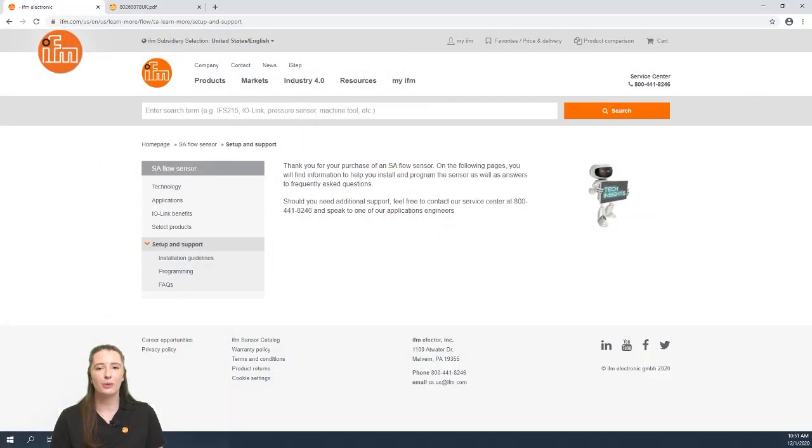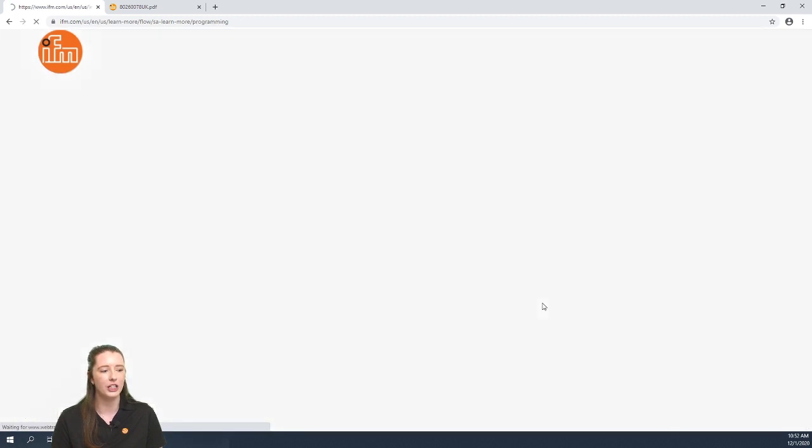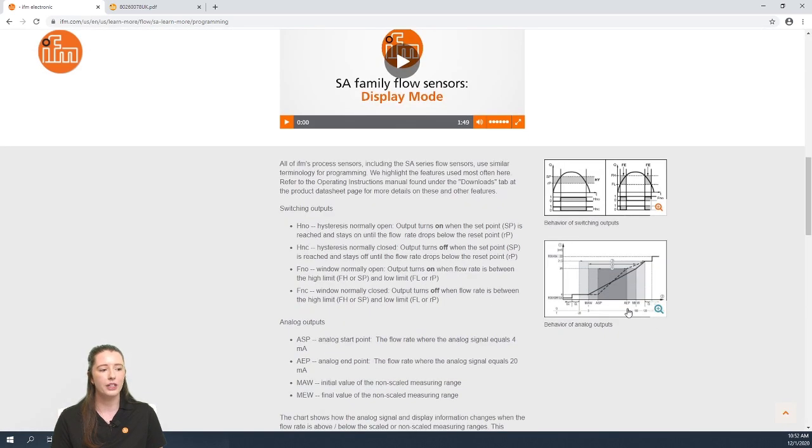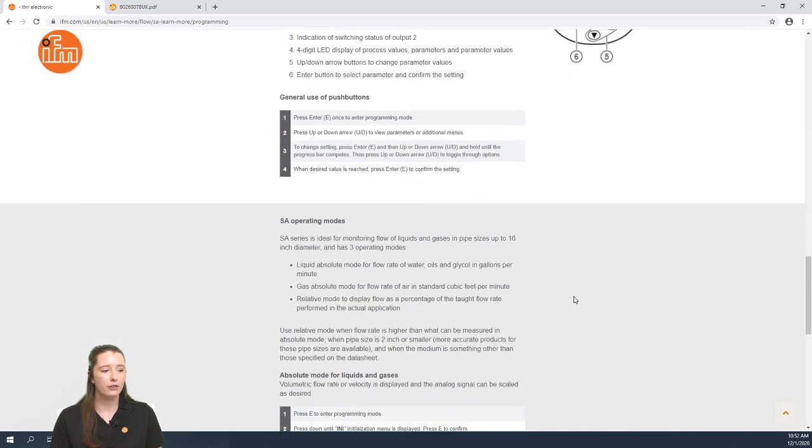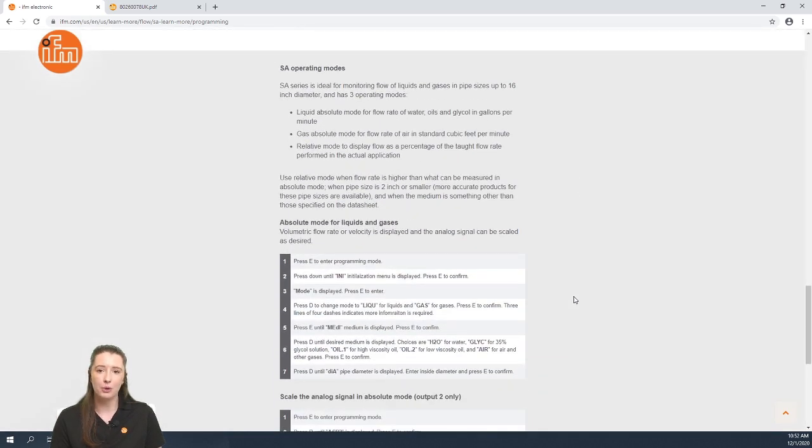In today's video, we are going over the programming of our SA series flow sensor. So let's get started. Here you have the Learn More section on our website for our SA series flow sensors. I wanted to show you this page where we define some of the commonly used terms in our menu structure. For example, we have HNO, HNC, FNO, and FNC, which are the different types of outputs used in our SA series flow sensor.